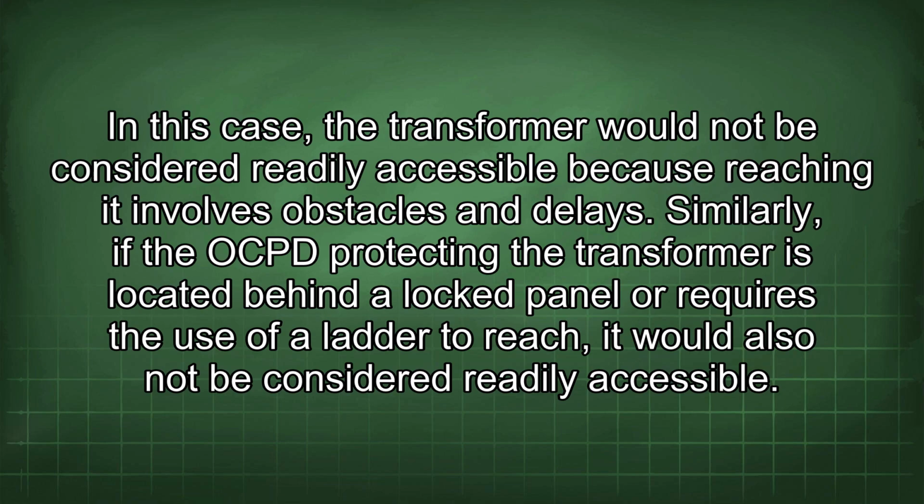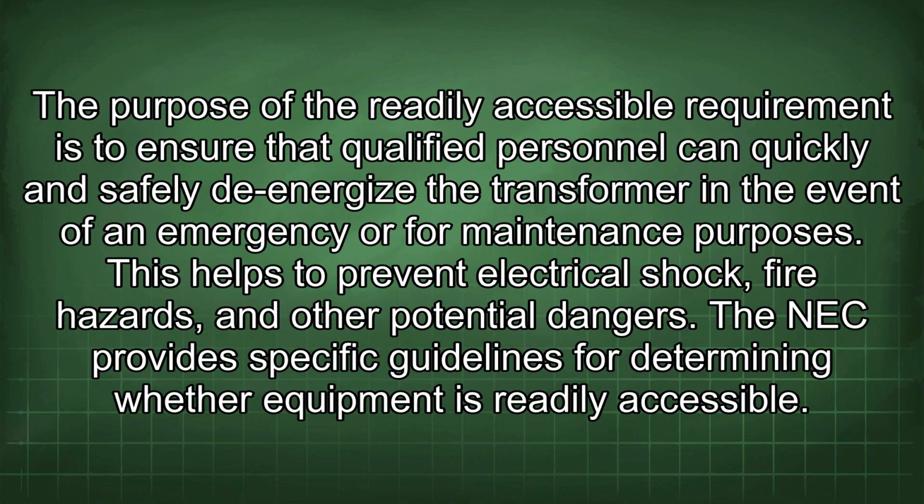Similarly, if the OCP protecting the transformer is located behind a locked panel or requires the use of a ladder to reach, it would also not be considered readily accessible. The purpose of the readily accessible requirement is to ensure that qualified personnel can quickly and safely de-energize the transformer in the event of an emergency or for maintenance purposes. This helps to prevent electrical shock, fire hazards, and other potential dangers.